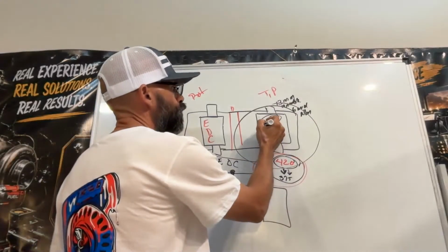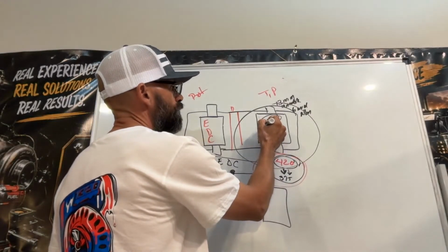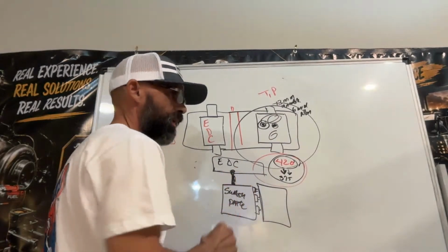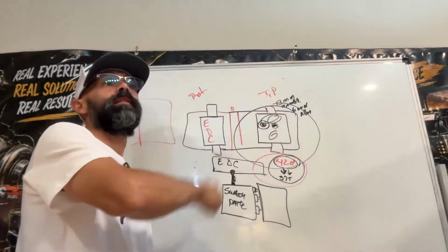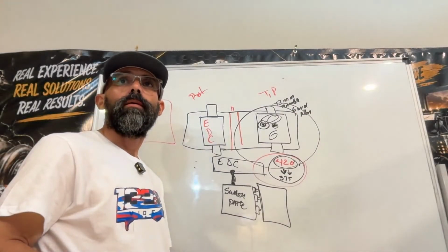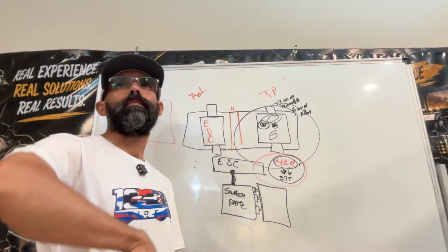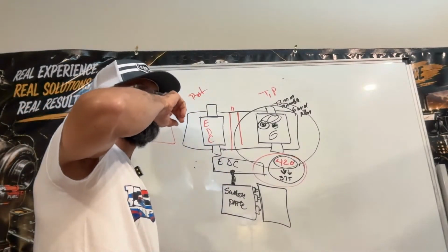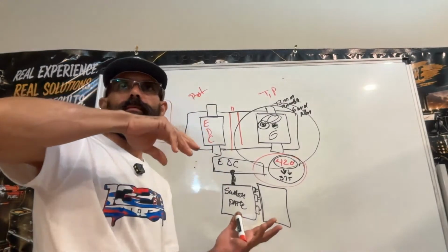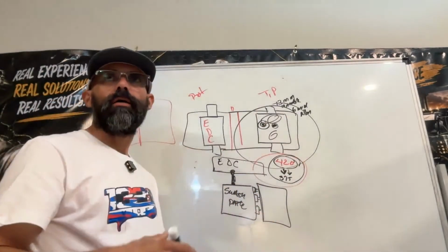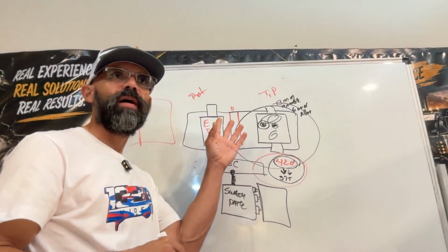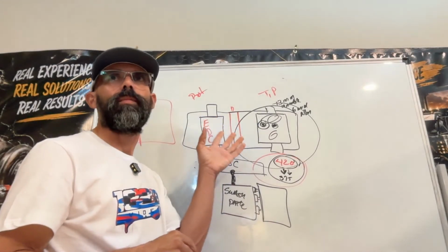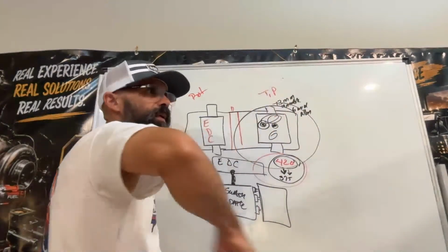Now, when you loosen the set screw for the control on the swash plate, you can spin that thing 360, and it's not gonna stop. You're not gonna be able to pull it out. Why? Because it's basically eccentric, right? So you're not gonna be able to pull it out like on the multifunction valves on a 90R pump or 90L pump. This set screw, you can spin it 360.